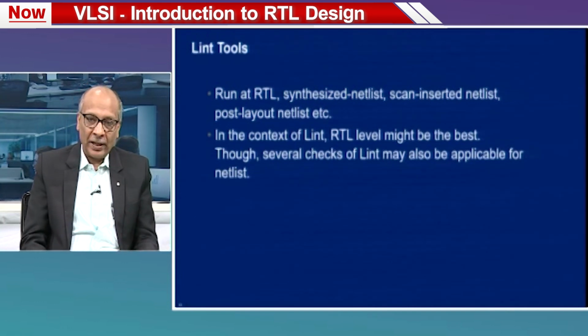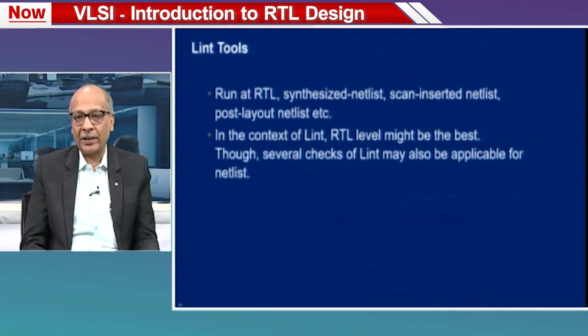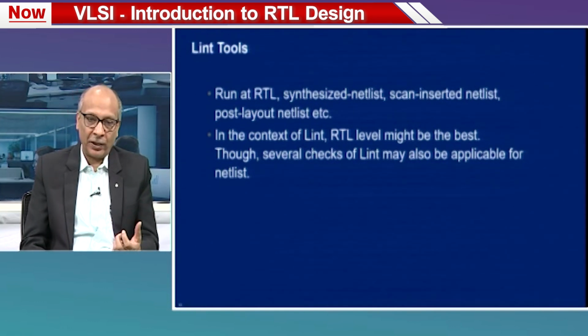While the linter tool can be run at RTL level and all kinds of netlist level, it is most popular at RTL level. Okay. Again, the logic is very simple. At RTL level, you want to catch your errors much upfront, and that is why lint tools are very popular at RTL level.